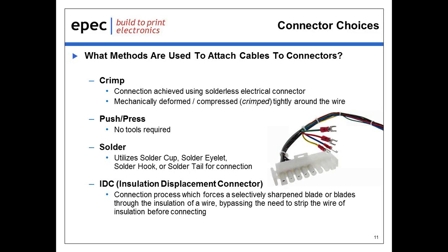A disadvantage to a solder connection is that it's the most time-consuming connection method and requires the person doing the soldering to be quite proficient at the process. A poor solder joint can fail due to mechanical or temperature stresses in the life of the assembly, so that's something we've got to be concerned about.